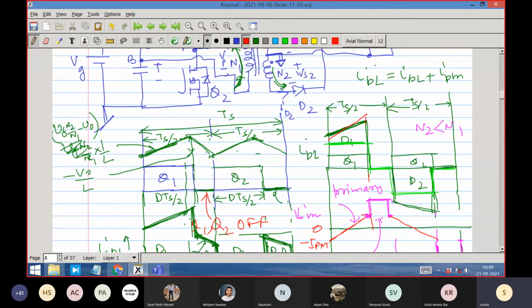And then, because you are bluntly, very drastically, switching on and off, there cannot be any current here, neither load current nor magnetizing current. But it is not a problem, because it is going to the secondary side. And the secondary side current will be slightly adjusted by the value of the primary magnetizing current. And why is the magnetizing current flat? Because actually in the transformer you are not applying any voltage across the magnetizing inductor. So its current is flat.